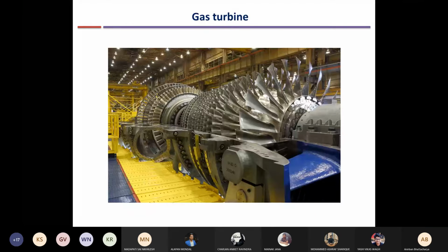Okay, so these turbine blades are there at the back, and they are rotating at very high speed. So they are undergoing a large amount of stress in the longitudinal direction because of centrifugal action, right? And so they are under large stress, and if you are at a high temperature at a constant stress, the creep will be higher.